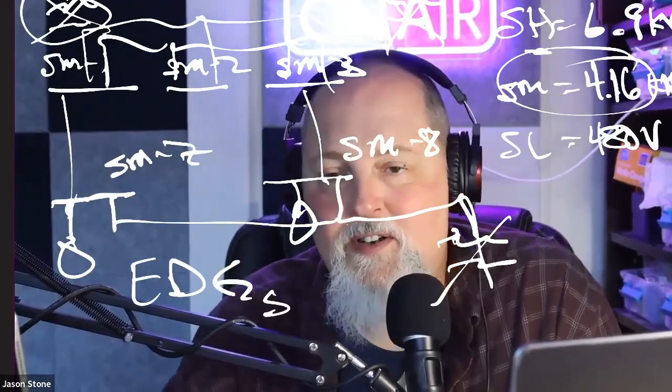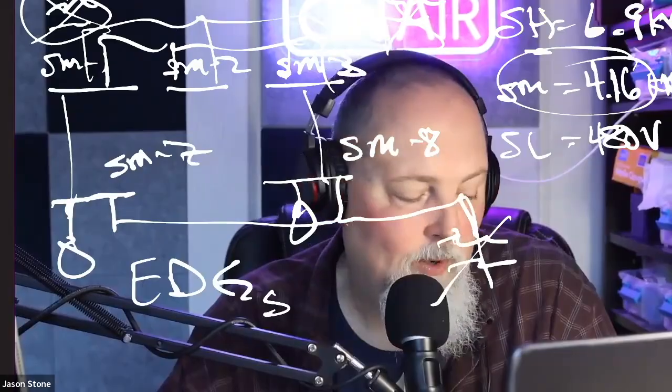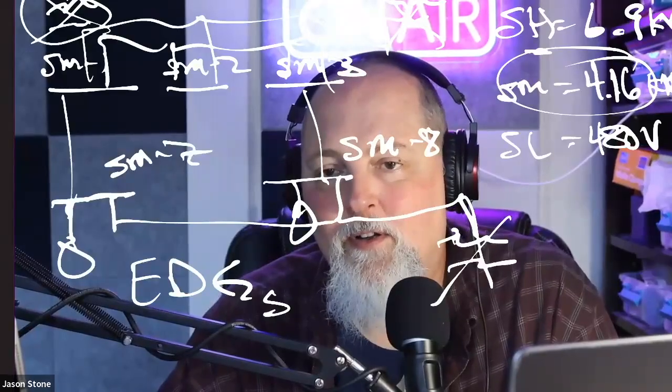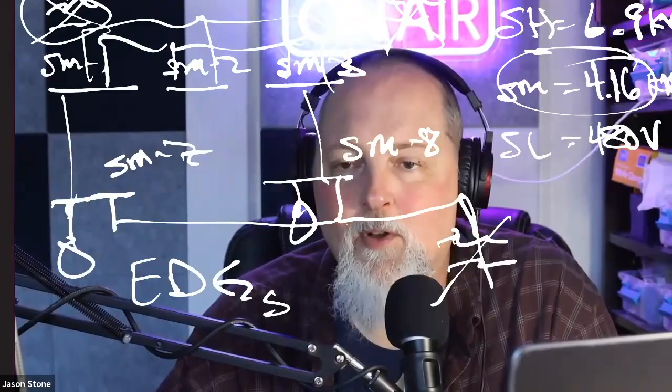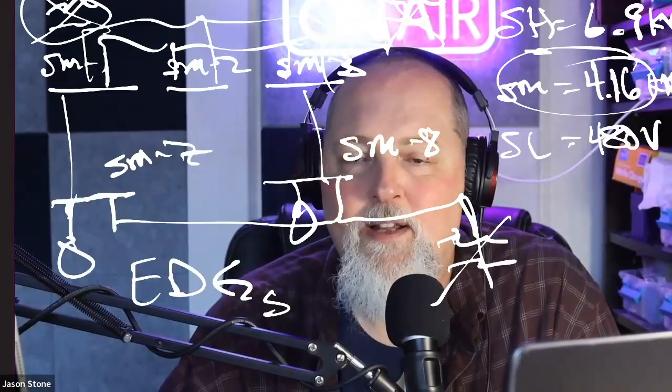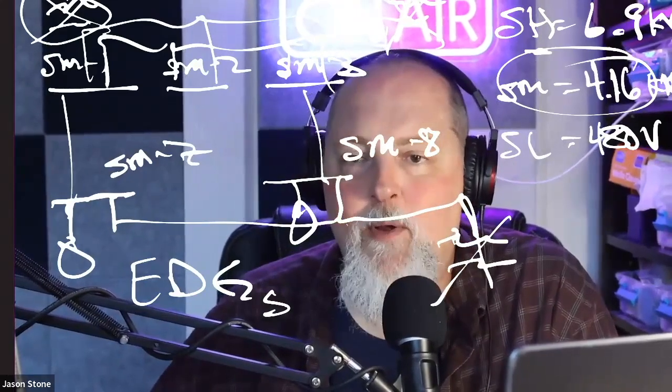This is a long story to get to the point of what an actuation is. Emergency diesel generators automatically start in the event of low reactor water level or high drywell pressure. And so that's an actuation. That's something starting that we want to happen.